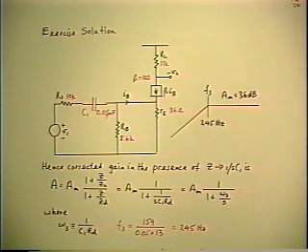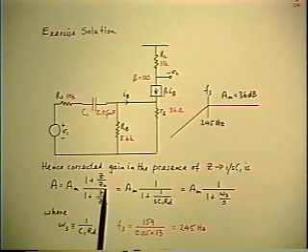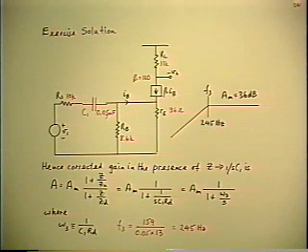Second, if the extra element is a pure reactance, such as a capacitor, the theorem correction factor gives you the pole and the zero immediately, because the Z is a reactance and the Zn and Zd are resistances. And you've seen that in most of the examples we've done already. The correction factor gives you the pole and the zero immediately.